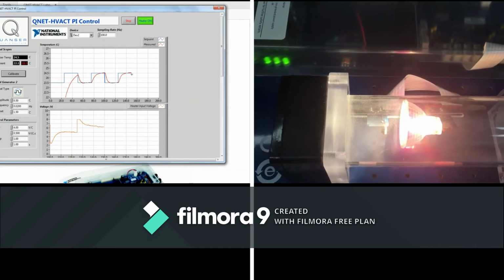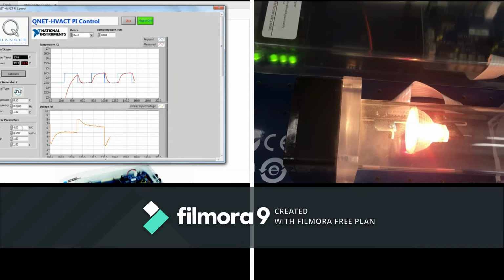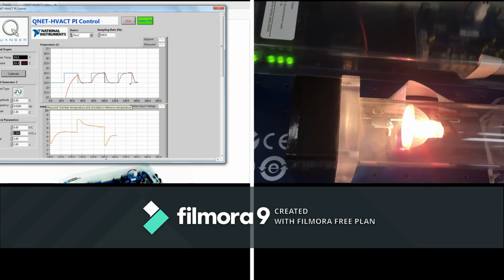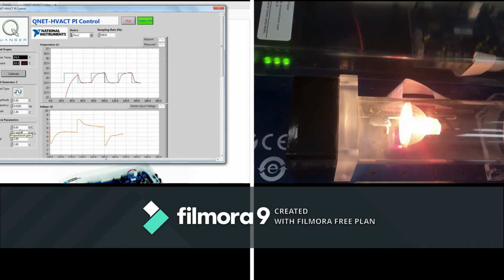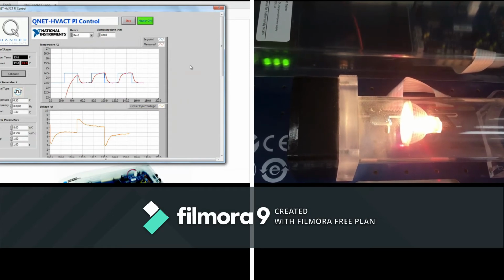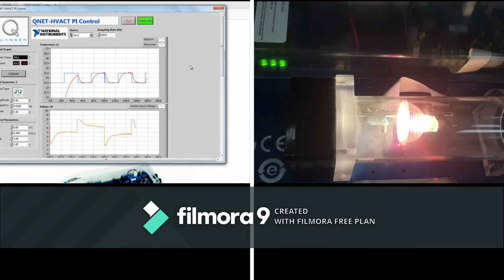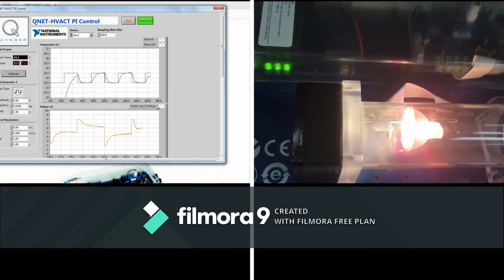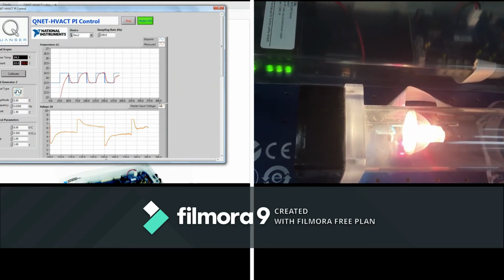So what will be the objective of this experiment? We want to study the effect of changing the parameters KP, proportional gain, and KI, integral gain, and their effect on the temperature response. So you see that if I just change KP to 8, for example, a random value, let's see how the next cycle will behave because of the high KP value. It seems like the rise time is faster, but let's just wait. Let me prepare that: instead of 200, let's look until 300, for example.